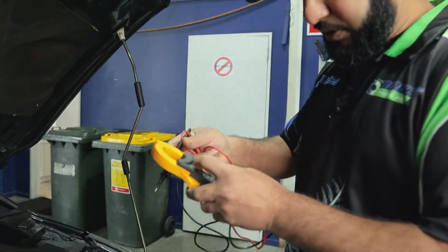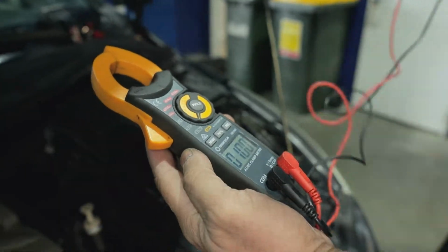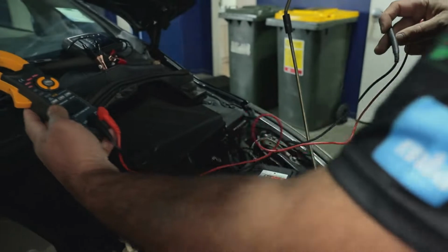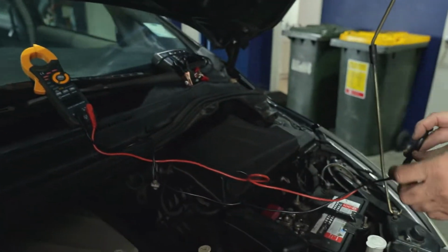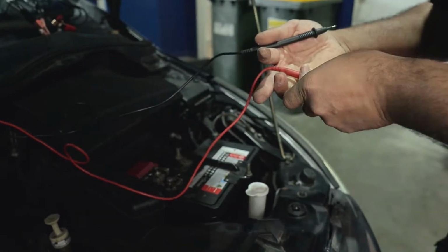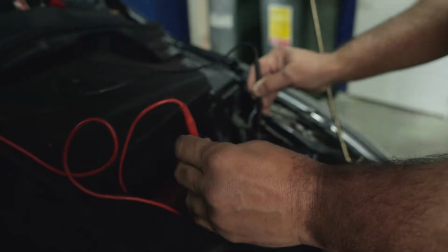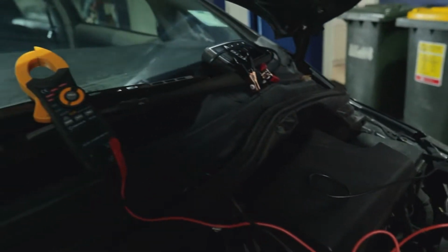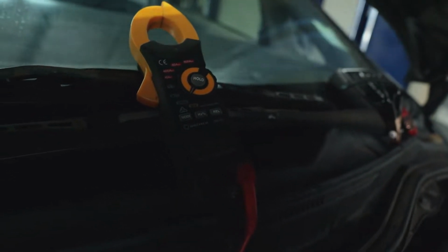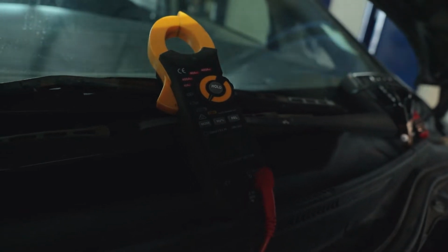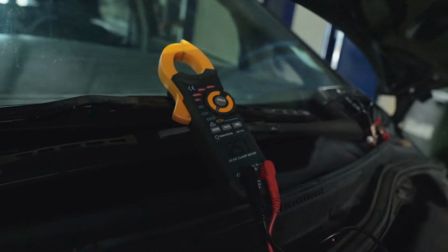This one here, we'll shift it on to volts. Quickly right there, make sure it zeroes out. All right, 0, cool. That's what we want. So we want to ground it first. So touch the negative terminal and touch the positive terminal. If we come up to the voltmeter, that one is at 12.51, which is a relatively good battery. 12.6 is fully charged, so that's close, and we count that as a good battery.